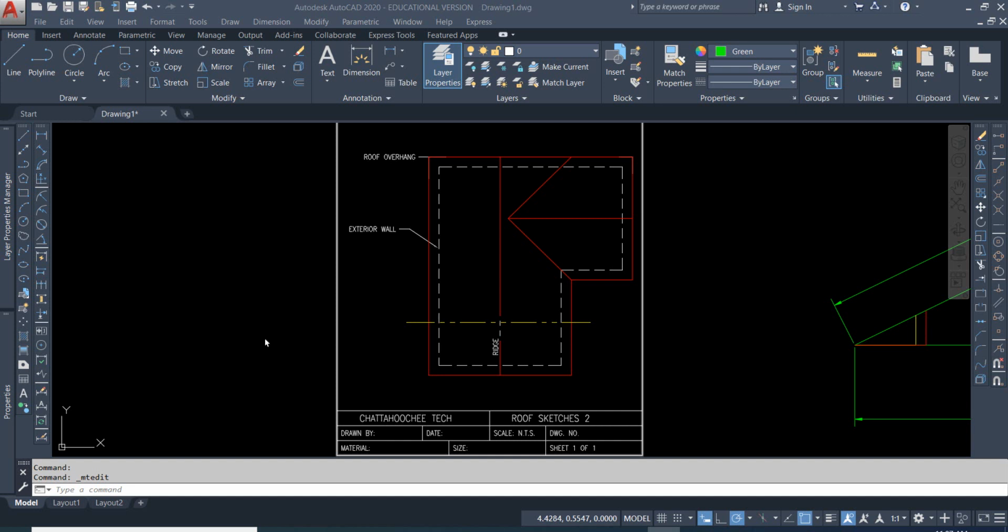So it's just basic math. You just set up a ratio using your roof slope to calculate the height and the hypotenuse. It's really that simple. So I've put a cutting plane line through here, and this is what you have to imagine you're doing: you're going to turn your roof up on the edge. So you're looking at it from the end, and you're going to see a triangle. You'll see an isosceles triangle, and we're going to cut that in half at the ridge, and that will give you a right triangle. Okay.